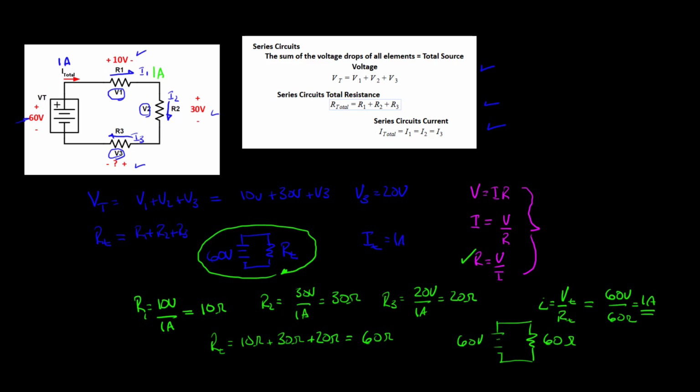Hopefully that clears up a few ideas for series circuits and helps you to solve your problems. If you use one of these steps for each one of your problems, you'll be able to solve it. The first few problems, we start out just using Ohm's law. After that, we'll ask you to look for the sum of the voltages and also to calculate the equivalent resistance. And always remember that the current total is the same throughout the circuit.